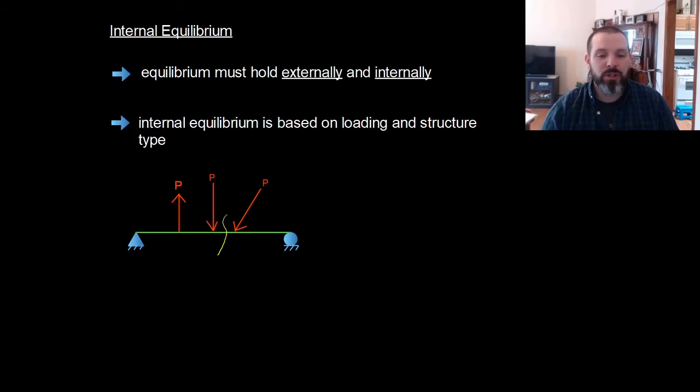Depending on how the loads are carried, the internal forces change and the requirements for equilibrium change. So when you make a section cut, you basically break a structure apart at a random point. So I'm going to cut between this force and this force.